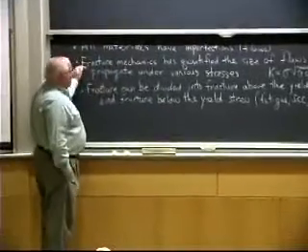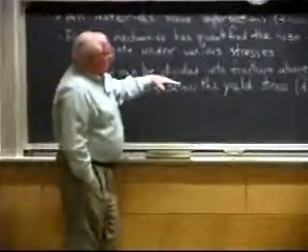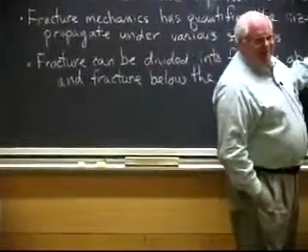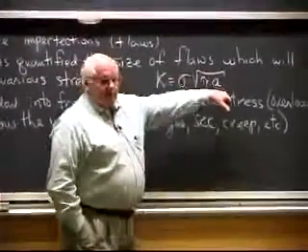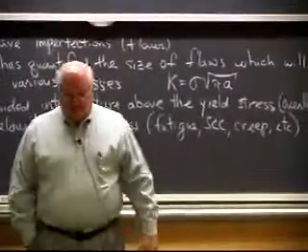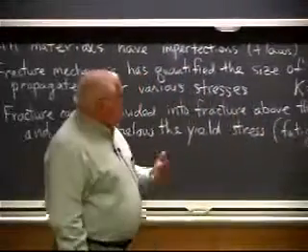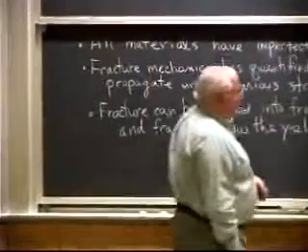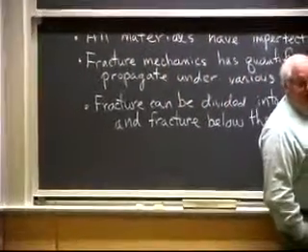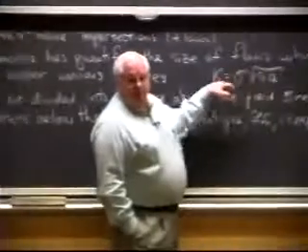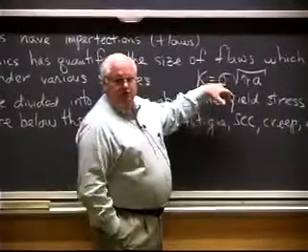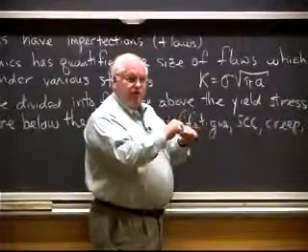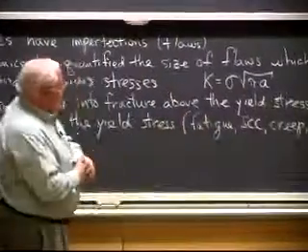And in fact, fracture mechanics tells us that the stress intensity, which is what's going to make the crack grow, is equal to the stress times the square root of the crack length. And there's all kinds of different geometries you have to go in that. There's different stresses, because you can have tensile stresses, you can have shear stresses, and the fracture mechanics calls that mode 1 for tensile, mode 2 for, turns out it's in-plane shear, and mode 3 for out-of-plane shear.